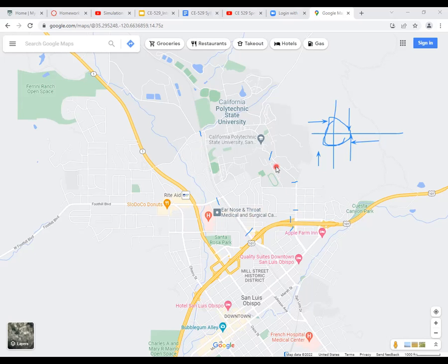So what you probably need to do is convert these traffic counts into some sort of origin destination flow, to figure out where this traffic is coming from and where it's going. So you need to allocate that level of traffic. What you need to think about is, what are my key origins for my network and what are my key destinations for my network?